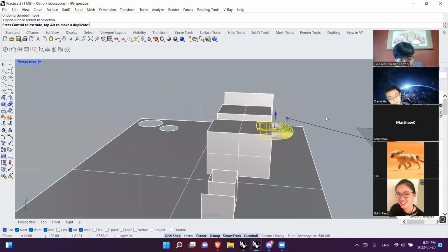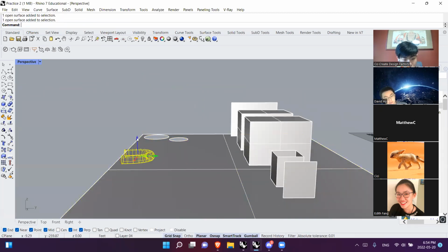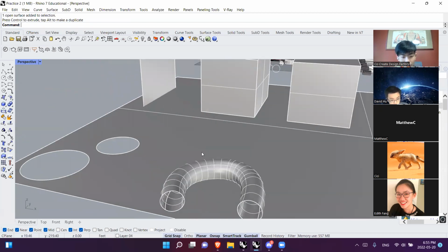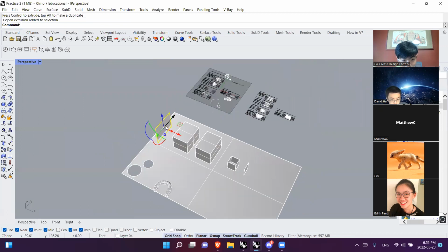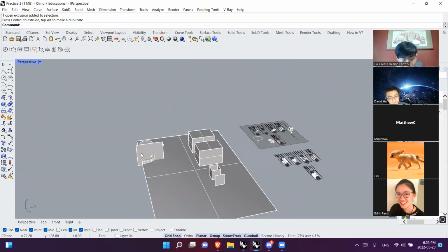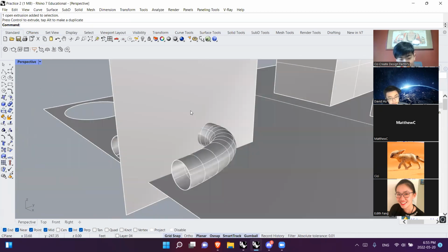And if you have a really complicated shape, let's use this, this is a good example. Move it up a bit. When you have this shape here, and this is why I saved it, our knife here still has uses, so we can cut it here. You can see that we have our tunnel here, but we also have our knife. So execute split, select objects to split. In this case, we want to cut our tunnel in half.